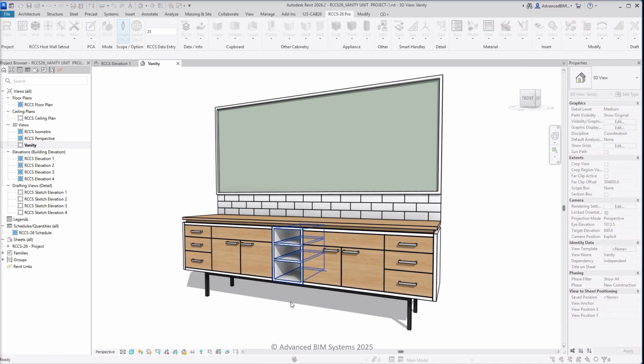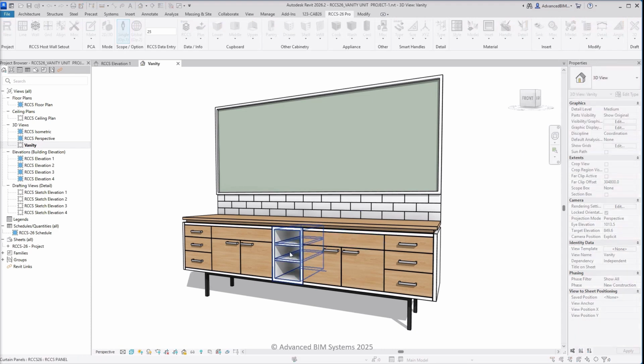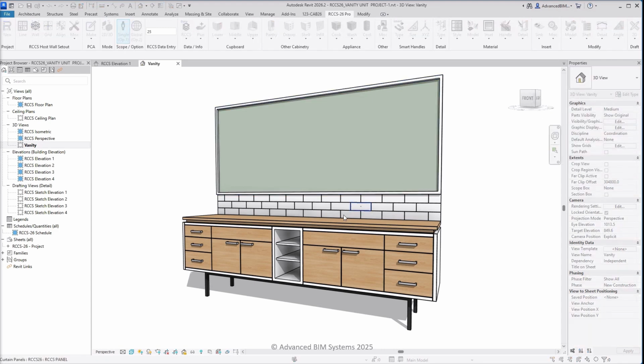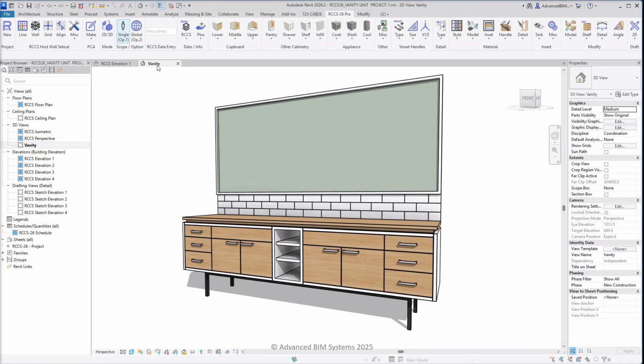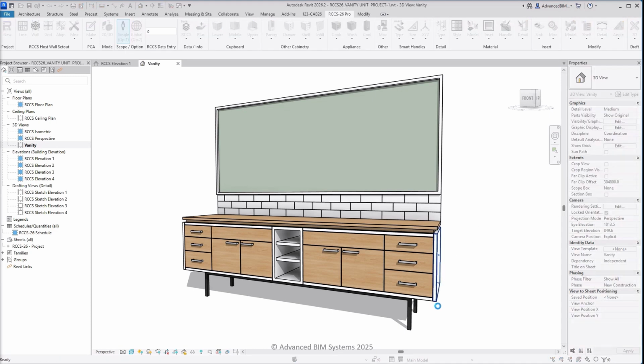The Width function can be used to change the shelf frame width. The Shelf Setback function offsets the front face of the inner shelves from the front face of the main component. Finally, adjust the inner shelf thickness using the Thickness function. Setting the outer edge radius to 0 will create a seamless transition between adjacent components.